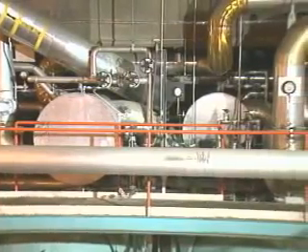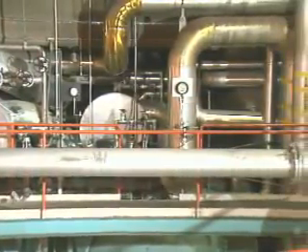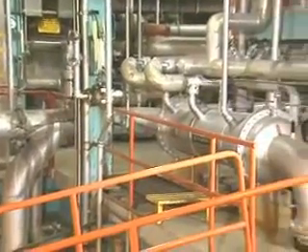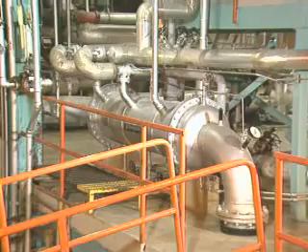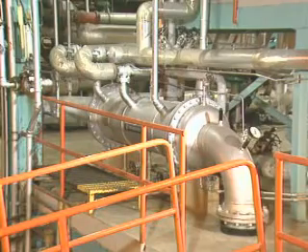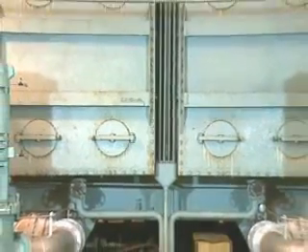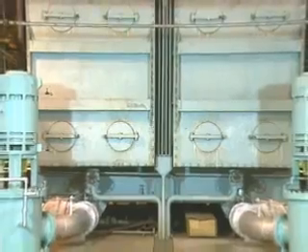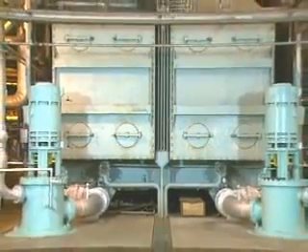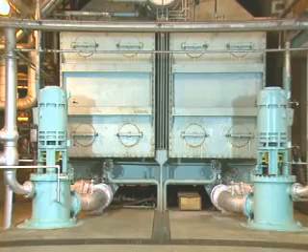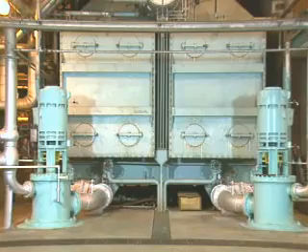Although the exact arrangement of components in a condensate and feed water system can vary, several pieces of equipment are common to most systems. In this part, we'll look at the major components of a typical condensate and feed water system. We'll begin with the hot well. The hot well is the bottom section of the main condenser. Condensate from the main condenser collects here and is then sent on through the condensate and feed water system, where the temperature and pressure of the condensate are gradually increased.